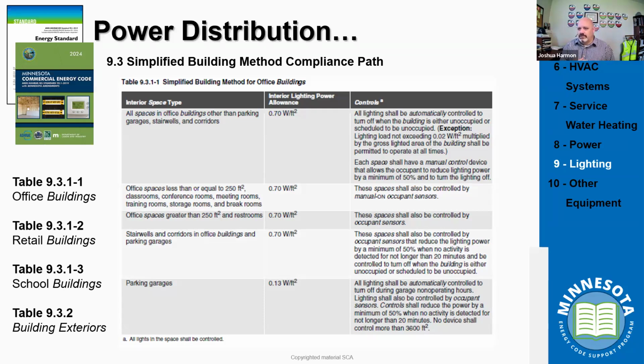So the question is, if a company is just changing out lighting to be more efficient, do they need to submit a COMcheck report? In my jurisdiction, no, because if they're just changing the fixtures, they're not doing any changes to the panel, anything like that. Generally not. Now, it may be useful for them to do a COMcheck so that they could calculate what that may do for them. And that's one of those conversations that I think most of us on here, as building officials, have, but that conversation changes over.